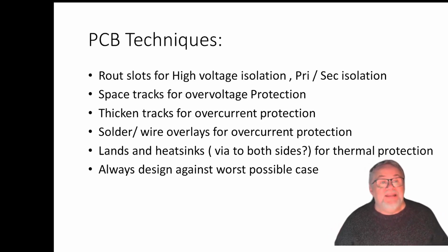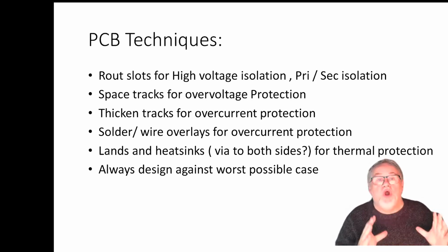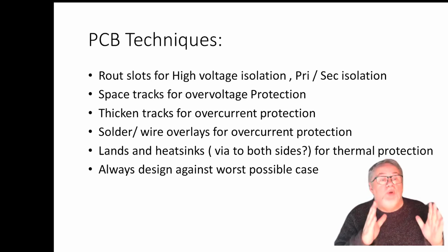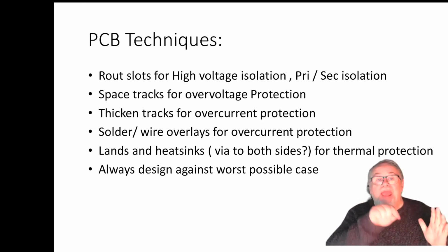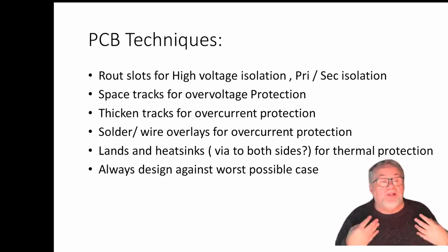You put lands and heat sinks. A land is, remember that area that was all covered in solder resist, the big green area on the printed circuit board, that's what you call a land. And you'll very often put a land with vias, little connections between the two layers of the board, so you've got a great big lump of copper to conduct heat away. And you always design a printed circuit board, not against the circuit as it's supposed to work, but against the circuit when it's got a fault on it. If that was shorted out, where would the current be?